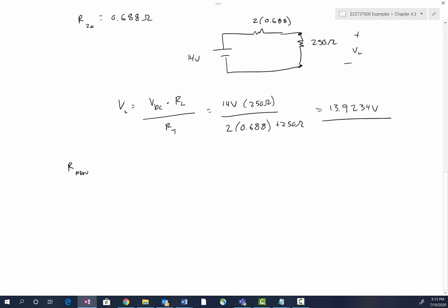If we had a table that was detailed, that's not usually typical. Instead, what we'll do is use a rating factor. The line resistance at 40 degrees C is going to be the 20 degrees measured temperature times 1 plus whatever the temperature coefficient of resistance is times the temperature change, the increase in temperature.